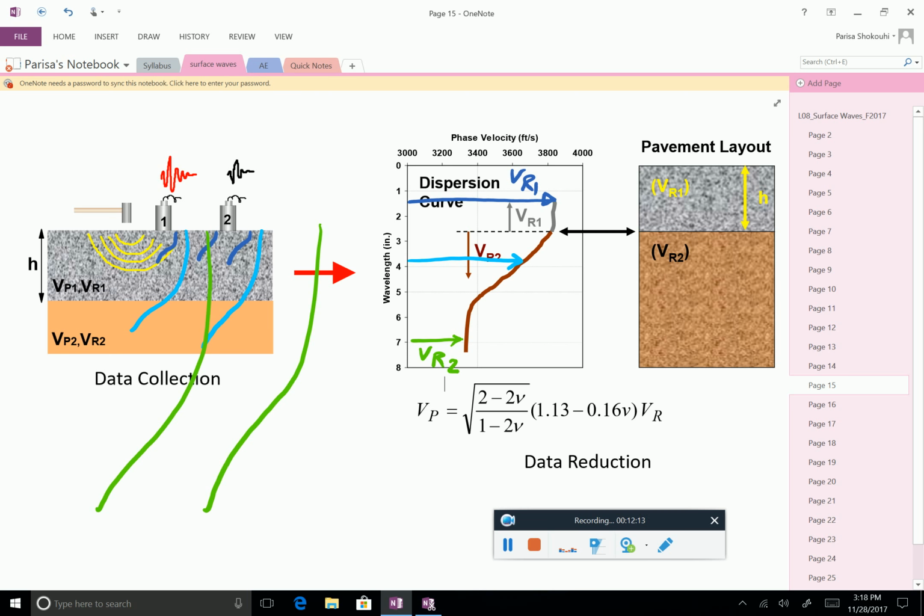And then you can look at this phase velocity versus wavelengths or frequency, and you see nicely how things are changing with depth. Because the nice thing is, if you plot this versus wavelengths, where you see a change is kind of where one layer is changing to the other, right? So it is actually quite interesting.